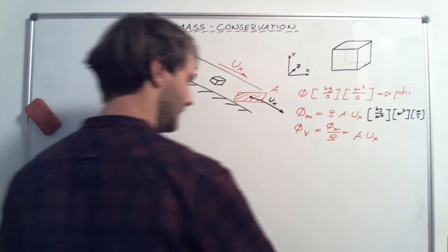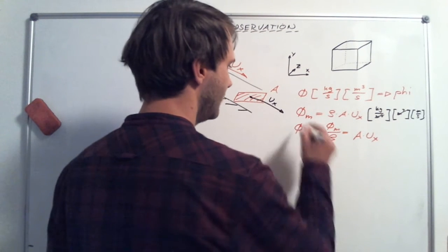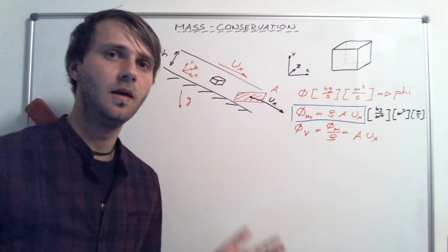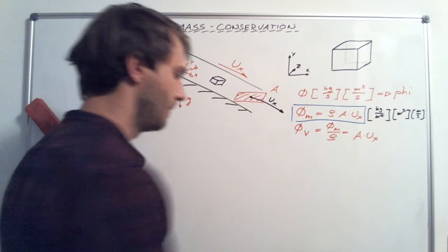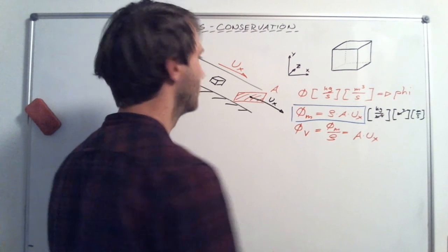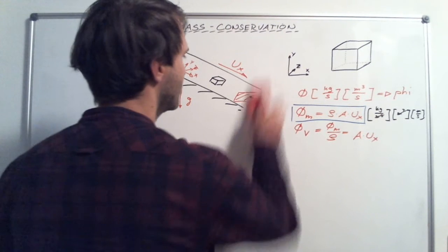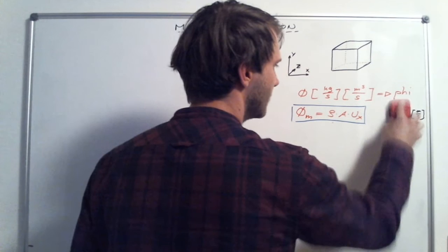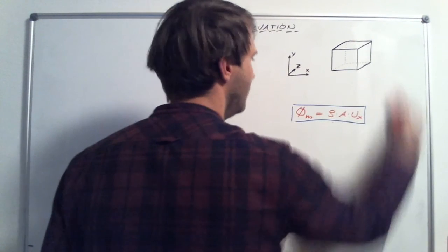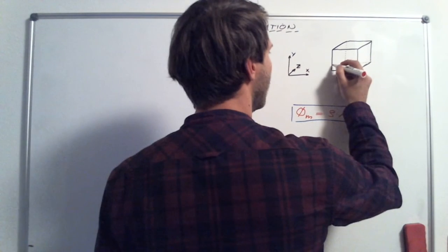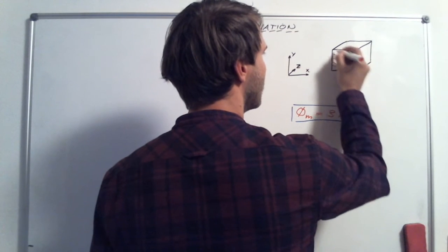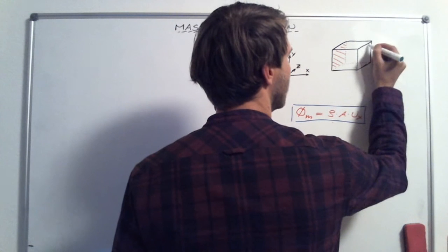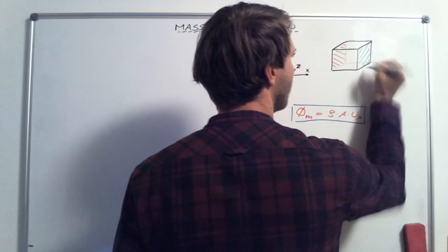So what do we need for the further investigation? We need to know how to calculate the mass flux on some area. So this was just for the beginning, and now things get easy and clear, so I think everybody can follow me. I will derive the mass conservation equation, in more detail, only in the x direction.